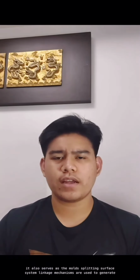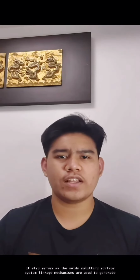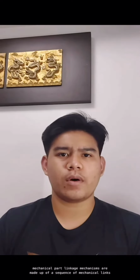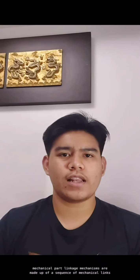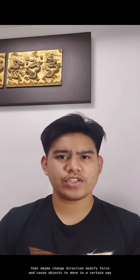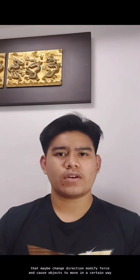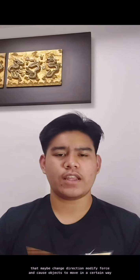System linkage mechanisms are used to generate rotational, oscillating, or reciprocating motion from the rotation of a crankshaft or a moving mechanical part. Linkage mechanisms are made up of a sequence of mechanical links that may change direction, modify force, and cause objects to move in a certain way.